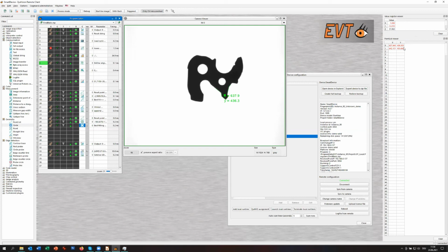So if you go through this, you have the matching tool, and in this case, we need another additional list. So you see here we have different other lists. In this case, we use the point register, not the point list. In the point register, we see the center point and the orientation point. The center point is here at the bottom of the arrow, and the orientation point is here at the end of the arrow. This gives us a point and orientation to adjust the coordinate system, which we see here now.